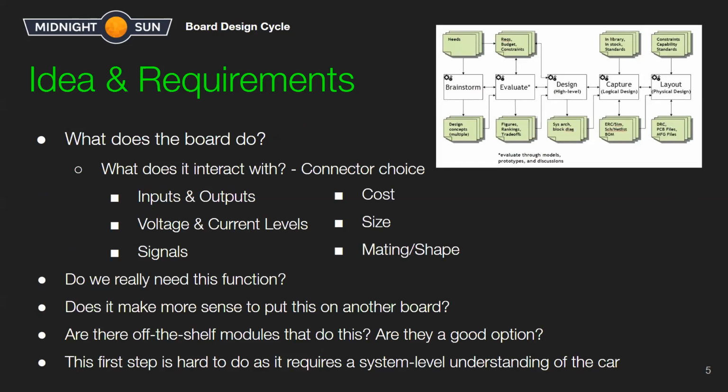And then you also have to be aware of the requirements on the connectors. The pin spacing has to be adequate for the voltage you need. Like the high voltage 150 volts, some of our connectors don't have quite as big of a margin. The Micro-Fits are good for up to 200 volts, and then other connectors will be able to handle higher voltage levels. Our car uses 150 volts max on its high voltage DC battery, but 200 volts is cutting it a little close. We'd like to be a little farther off of that, having connectors that are at least rated for 300 volts or so when we're dealing with high voltage.